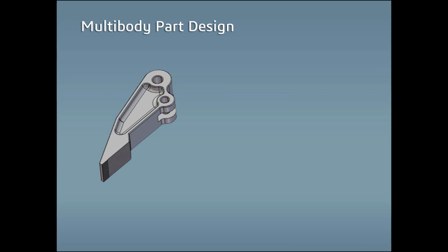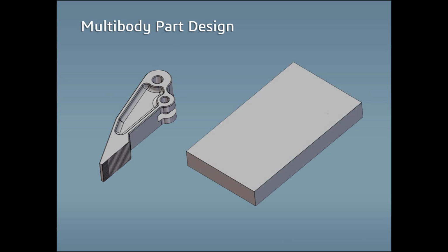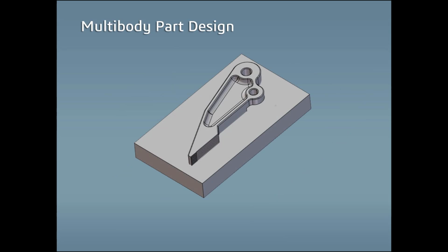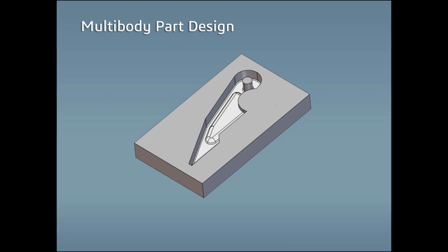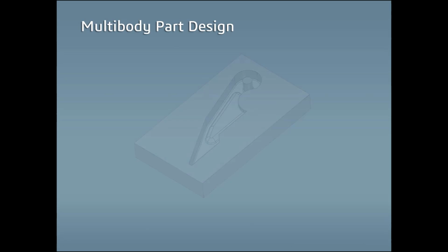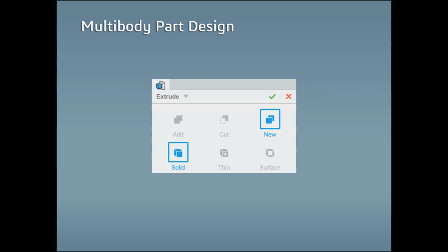One of the ways you can create unique geometry is by using multi-body designs that can be combined and subtracted from one another. Rather than having to model a complex surface or cutaway feature on a single body, you can overlap bodies and combine them or remove the overlap from them to create the geometry you're looking for, all using a single command. In this lesson, I'll walk through how you can create a multi-body design by changing some of the options in the sketch-based features.